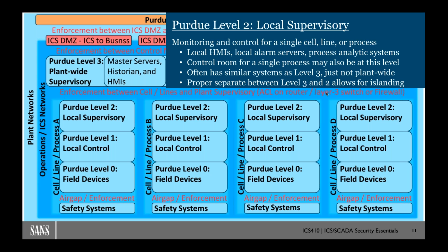So that's my recommendation. Still have them connect through that cloud demilitarized zone, and then from that cloud demilitarized zone, build little tunnels, which 62443 calls conduits. Build that conduit, or a VPN, or some type of network link so that it directly connects to the device that they need to manage themselves. The biggest goal here is to minimize the risk of an attack coming through the cloud solution from affecting the rest of the plant.